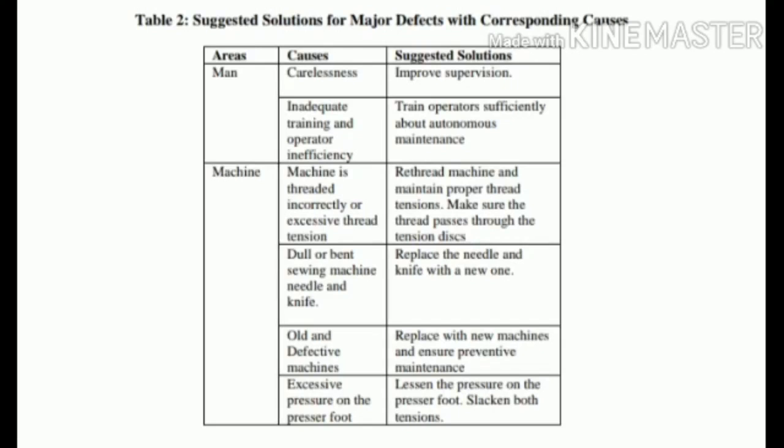Another area is the machine. Cause: machine is threaded incorrectly or excessive thread tension. Solution: rethread machine and maintain proper thread tension. Make sure the thread passes through the tension discs.